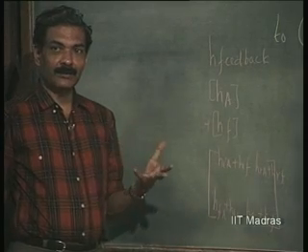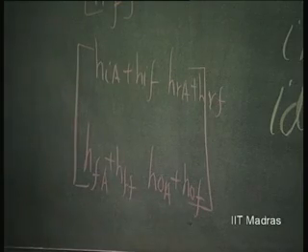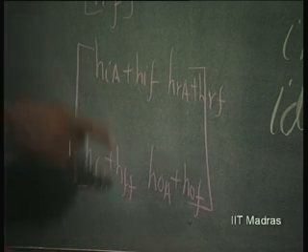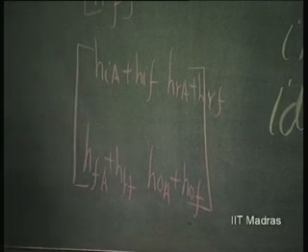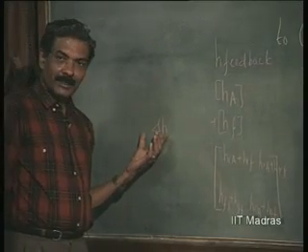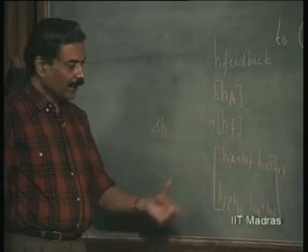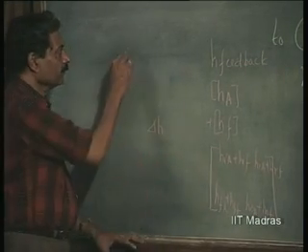How will you convert it into G? Then you will take the matrix here, you can invert it, right. So, you will take the determinant of this matrix, delta H, and obtain the G parameter. What will be the G I?